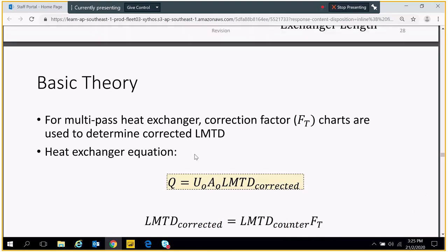Then the same thing for the distillation column. For the distillation column, you want to achieve a purity of 96 mole% for benzene. What is the minimum external reflux ratio? What's the minimum L over D to achieve the 96 mole%? Why do you want the minimum? Because with minimum L over D, your distillate flow rate D is the highest. D is highest is good because you get more production per hour, and at the same time, you can achieve the 96 mole% benzene. That is good. That is optimization.